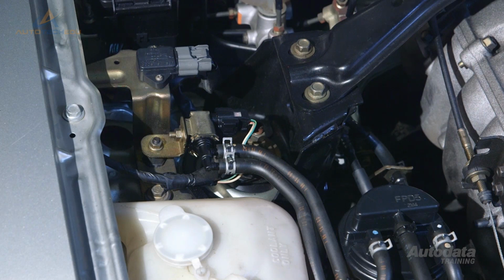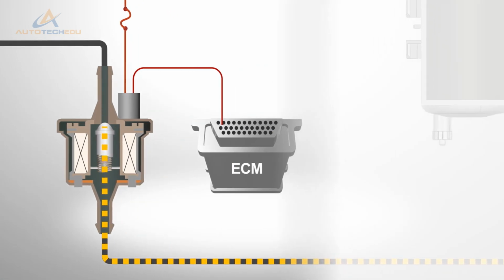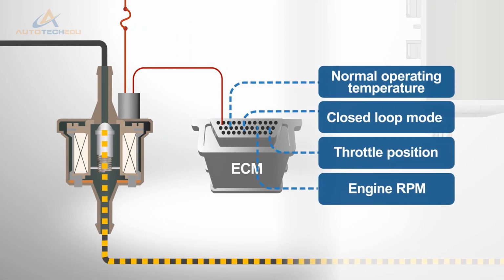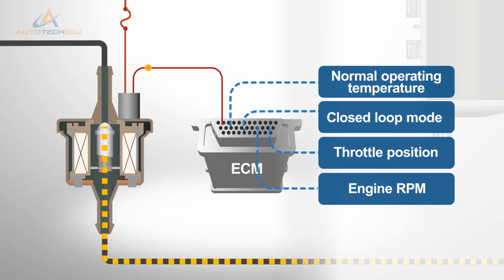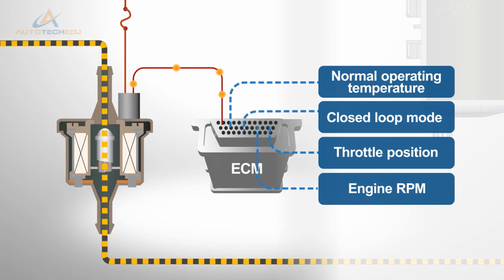These systems use a purge solenoid valve that is duty cycle controlled. The purge valve is only opened when the ECM determines the engine is at the correct operating temperature and in closed loop mode. The engine can then utilise the enriched fuel mixture, this time without affecting performance or emissions. These systems allow precise control of vapour volume and flow, so when purging, drivability is not altered.